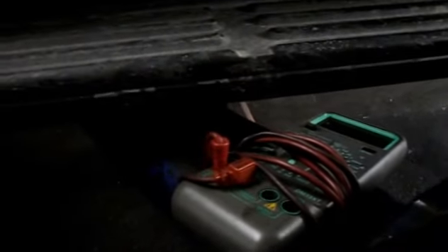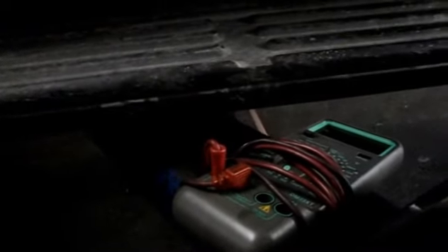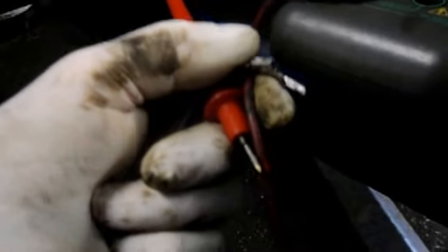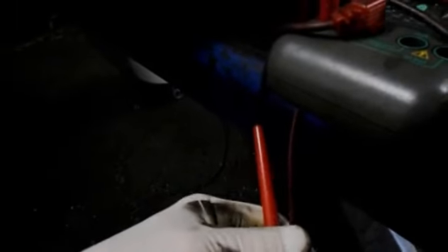Okay, now we've got the truck up on the lift, and just so you know, on this particular vehicle the vehicle speed sensor is underneath, on the back half of the transmission, around where the shifter linkage goes into the trans. We're going to need an ohm meter to check the resistance on the sensor, and we're also going to need some electrical plugs, because it's going to be hard to get in there with these ends here to check the resistance.